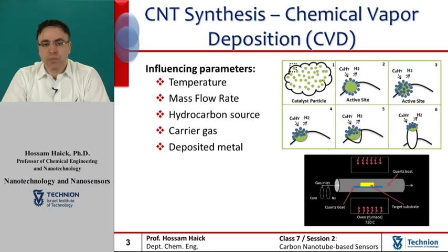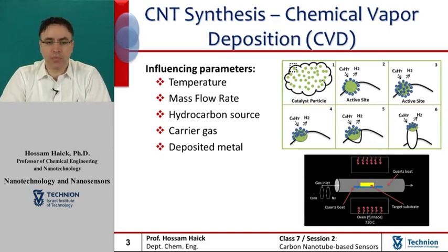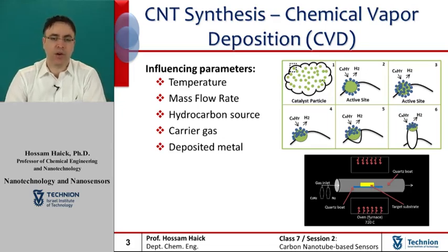Schematic description of the process is illustrated in the upper image on the screen. A substrate seeded with metal catalyst is exposed to a gas containing carbon. The system is then heated up to several hundred degrees Celsius until it disintegrates and single reactive carbon atoms are generated.